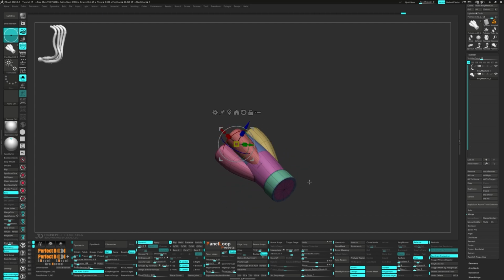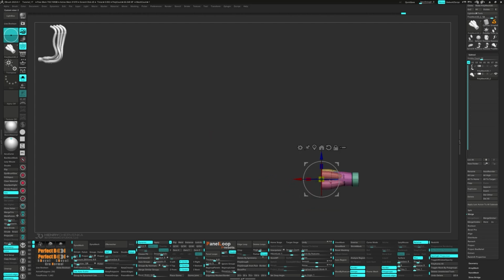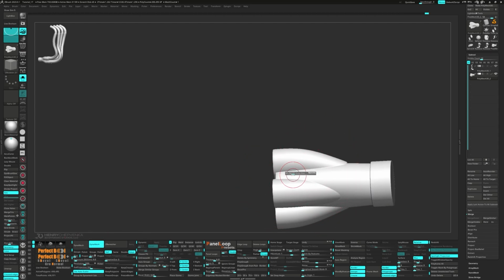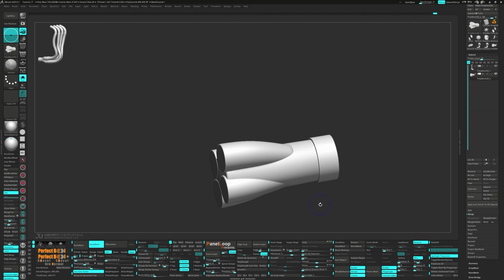Press QC50 and make a few scaling adjustments. Now we can press Apply and set the Dynamesh utility poly count to 0.5. Let's turn off Mask by Polygroups and set the weighted smooth mode to 1.